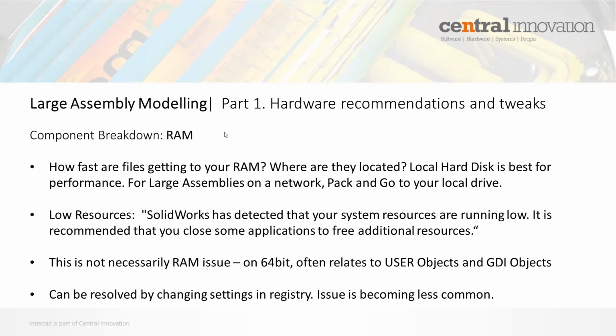We do also get a low resource warning from time to time. SOLIDWORKS has detected that your system resources are running low. It's recommended that you close some applications to free additional resources. This is not necessarily always a RAM issue, particularly on 64-bit machines. It's more often related to user objects and GDI objects, which is a Windows setting. If you're getting this type of error, it can be resolved by changing some settings in the registry, but what I would say is that if you do get that warning coming up, then it's probably best to contact us for further assistance with that issue. By and large, it's becoming less of an issue as people are switching to 64-bit and using larger amounts of memory on their system.